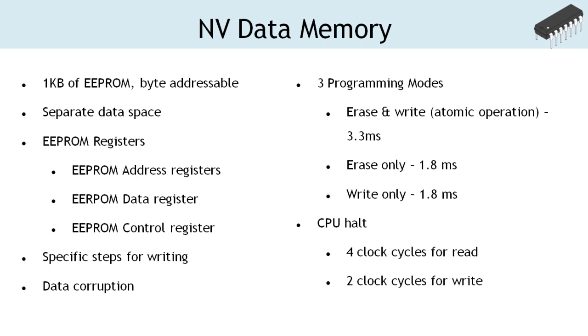In most variants of the AVR architecture, this internal EEPROM memory is not mapped to the addressable memory space. It can be accessed as an external peripheral device using special registers with read and write instructions. This makes EEPROM access much slower than the data and program memory.